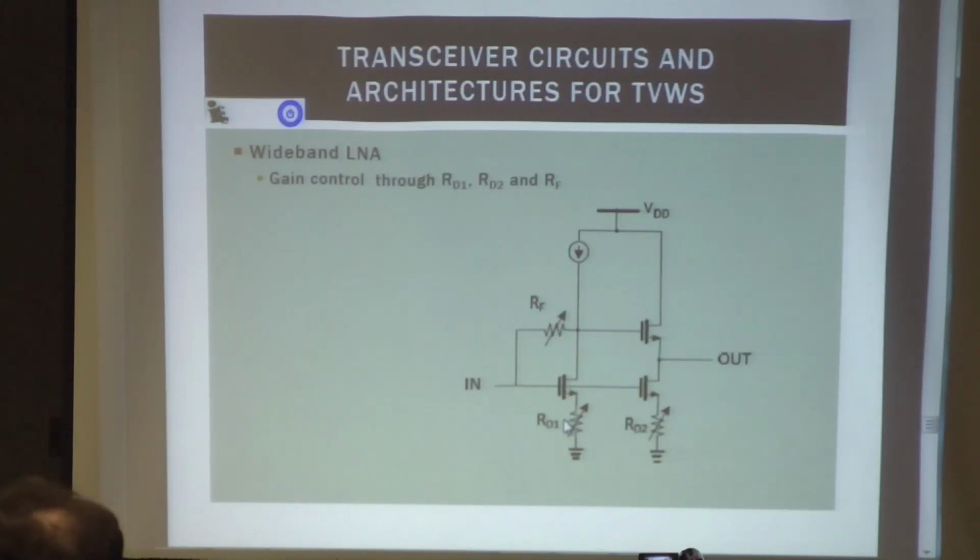And this is an example of an LNA. That's how you could program it, an LNA that has wideband and programmable gain. You basically make your feedback resistor programmable and the gm resistors also programmable.